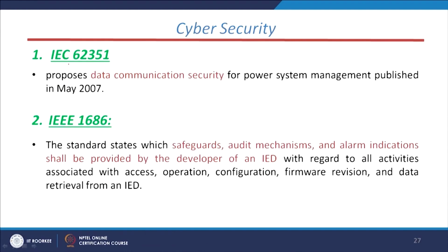And this is part of cyber security. This is my last standard, IEC 62351 and IEEE 1686, these two are dedicated to this. The first one designs the data communication security, and the second one provides the safeguard audit mechanism and alarm indication, which shall be developed by the developer of an IED with regard to all the activities associated with operation, configuration, and data retrieval from an IED. IED means intelligent electronic devices.